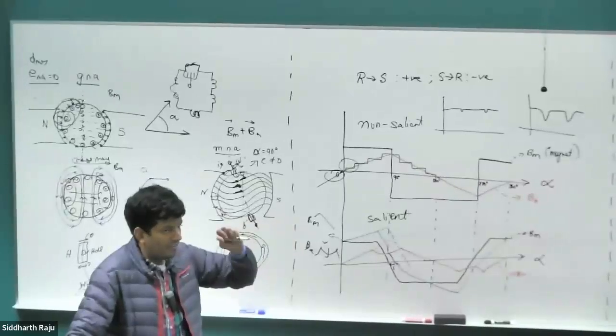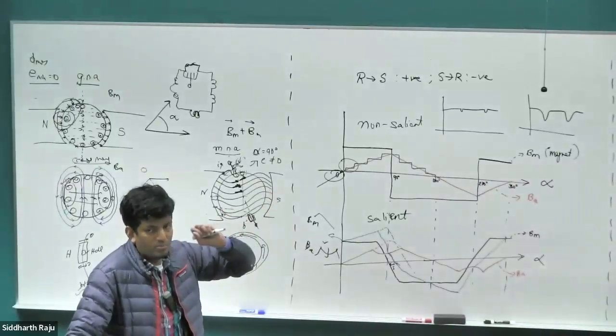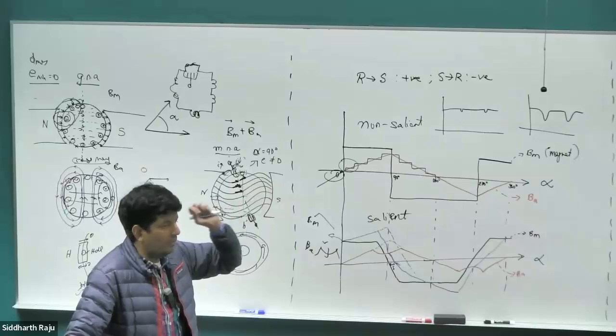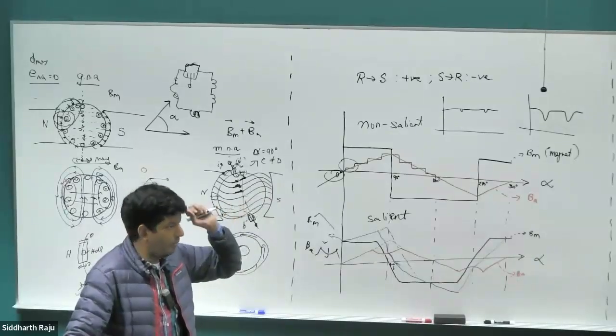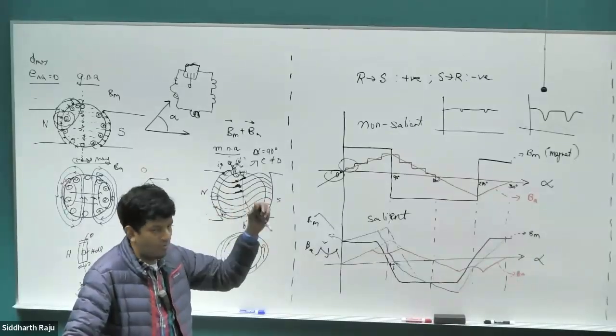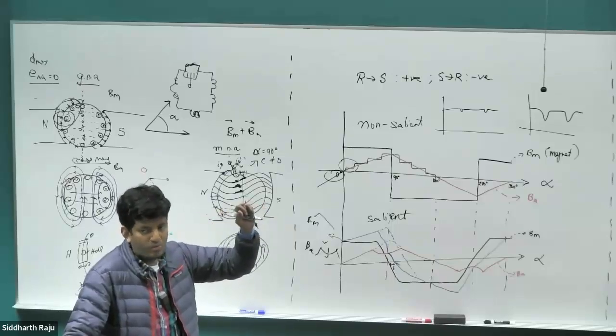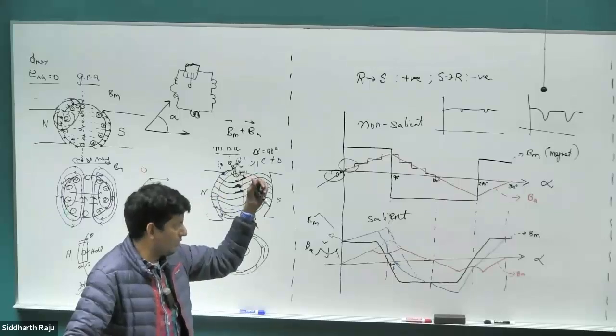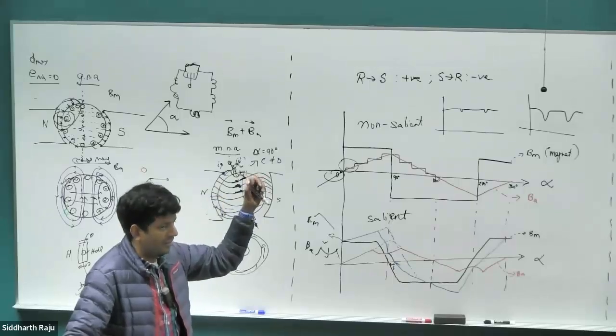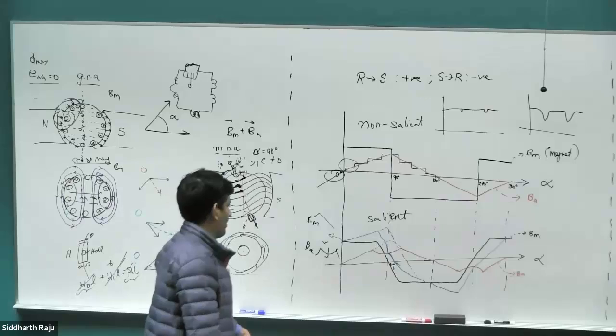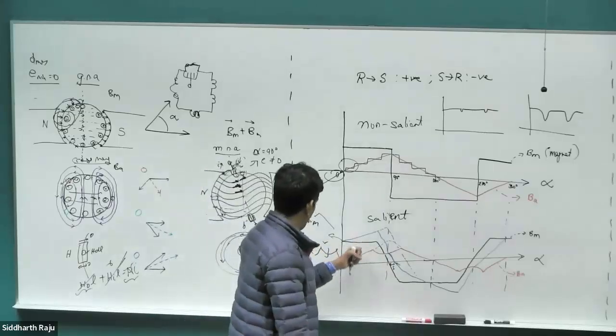For instance, let's say you have an iron core and it has gone into full saturation. Let's say you push 2.3 Tesla. No matter what powerful magnet in the world you can bring in or you put an extremely powerful coil, the magnetic field in the iron core is not going to increase past 2.3 Tesla or 2.5 Tesla. You're going to require enormous amounts of current to push it any further, right? It doesn't operate linearly at that point. So we cannot just simply add these 2 values together.